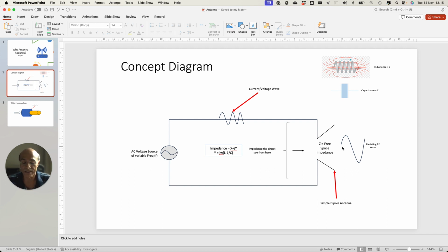But again, the size of the disc and the structure of the overall system is inversely proportional to frequency, that is, it is directly proportional to the wavelength. So basically what I am trying to say is that if you really want your signal to be of better quality, you have to increase the size of the antenna. The shortest antenna size is going to be lambda by 4. But let's say you want a very good quality signal, noise is extremely high around you, and you are receiving a signal of very, very low power, then you have to have a disc of very large size. You might have seen this, when satellite receivers or even telescopes have a disc which is very, very significant.